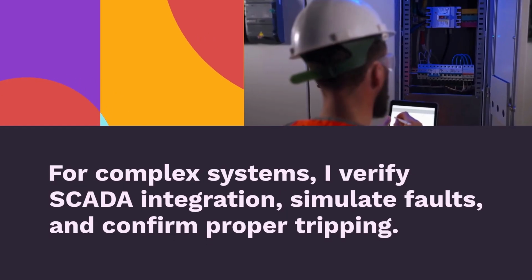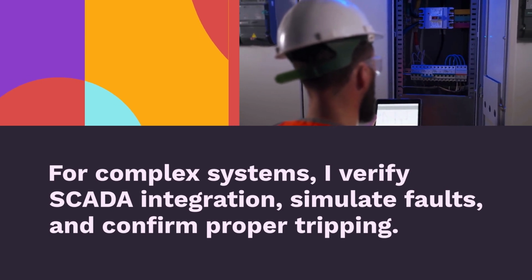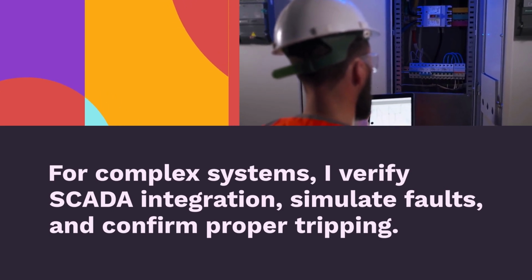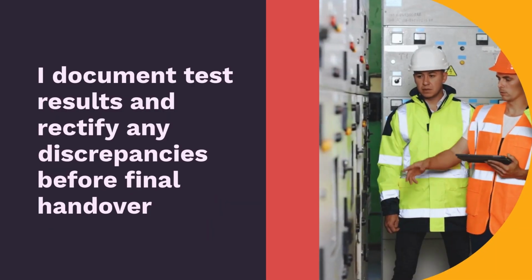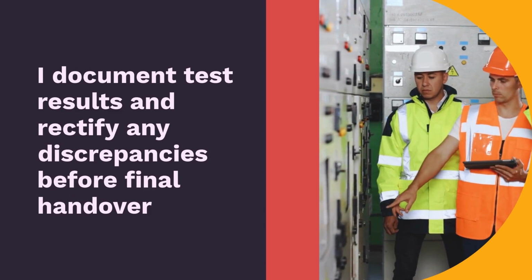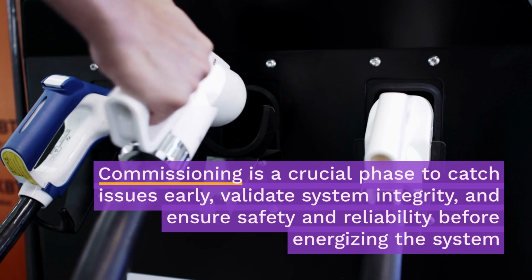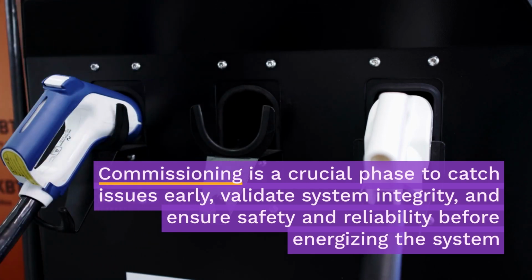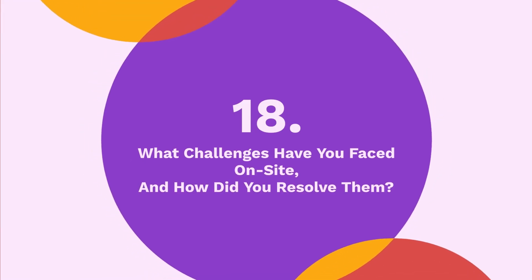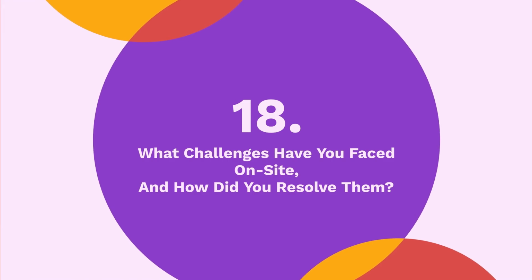For complex systems, I verify SCADA integration, simulate faults, and confirm proper tripping. I document test results and rectify any discrepancies before final handover. Commissioning is a crucial phase to catch issues early, validate system integrity, and ensure safety and reliability before energizing the system.